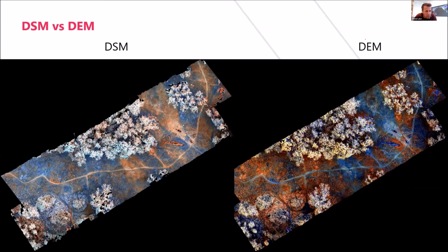You are flying in two different directions here. You have a good match here, but in the trees you don't. You can see the tree suddenly stops, right? So you don't have good co-registration here because you're using the ground elevation to do the ray tracing. While here you're using the surface model and you have good overlap on the ground and in the trees.